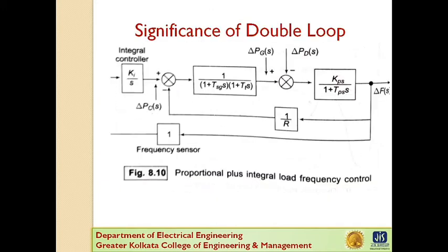Now it is evident from our previous discussion that with the speed governing system installed on each machine, the steady state load frequency characteristic for a given speed changer setting has considerable droop. In the previous case we saw a steady state droop in frequency of 2.9 Hz from no load to full load.